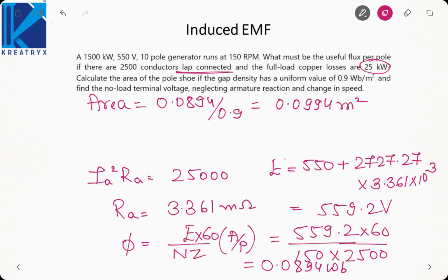What about the no load terminal voltage? That is 559.2. Why is it the no load terminal voltage? Because under no load, terminal voltage is equal to induced EMF.